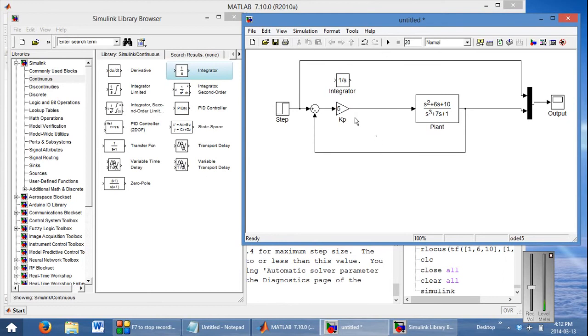So one thing we can do, we can select a block, press Control, and then drag the block off of there, and then you will see that your mouse pointer changes into a plus. This means that you're going to make a copy. And then when you let go of your left mouse button, it creates a copy and renames it to something else. So here we want KI.